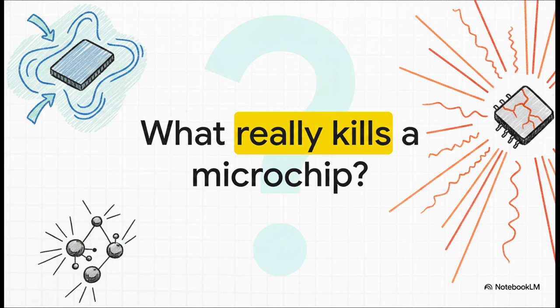So, what really kills a microchip? Well, in this high-stakes invisible war, defects basically stem from three foundational root causes. We're talking about fluid flow anomalies, which involve issues with the protective underfills, metallurgical dynamics, which center on the tiny solder joints connecting everything, or extreme thermomechanical stress.